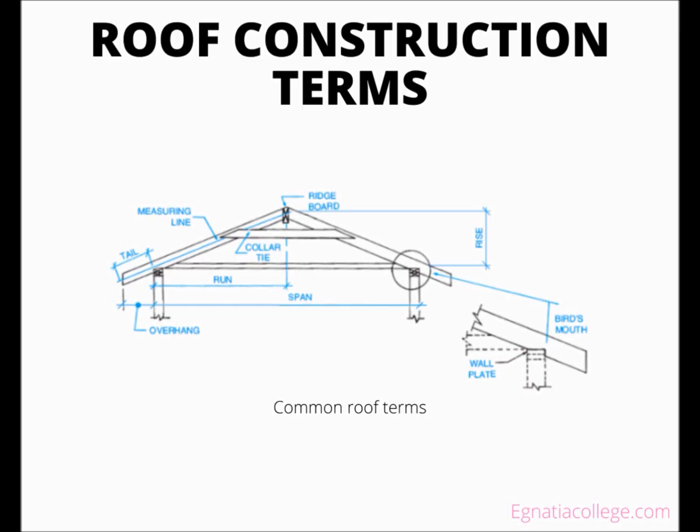The designer can make the roof width fit the 2-foot grid by adjusting the slope of the roof. When the dimensions are given for a run of other than 12 feet, the rise per foot of run can be calculated. Divide 12 by the actual run to find the proper ratio of rise. Multiply this result by the actual rise to find the rise per foot of run.